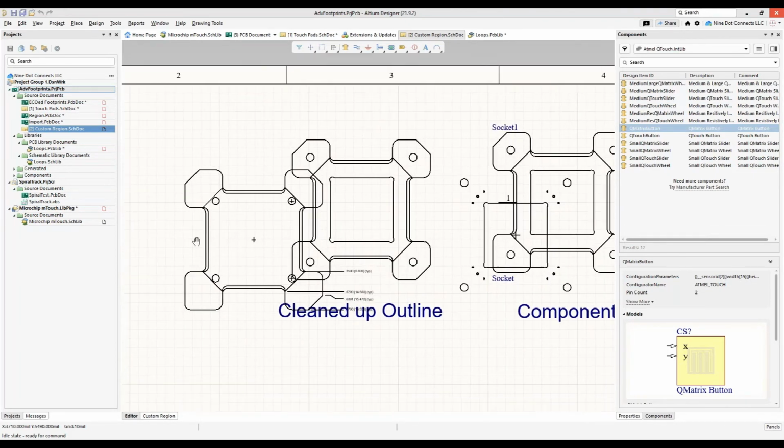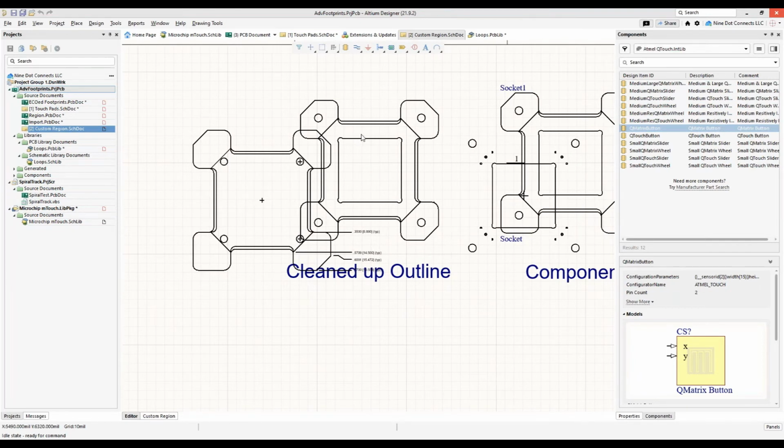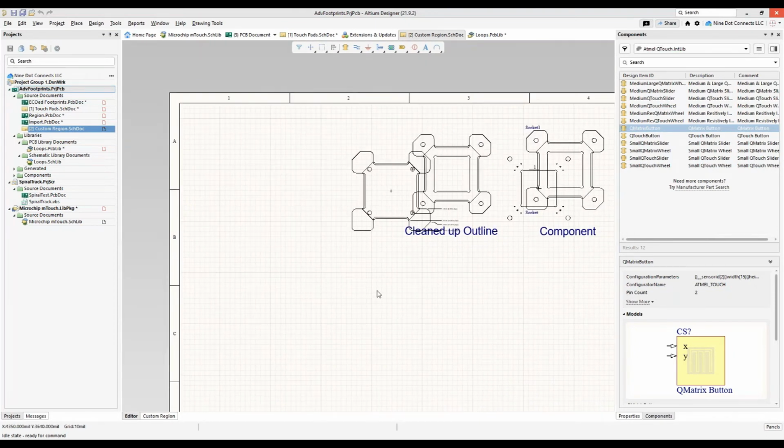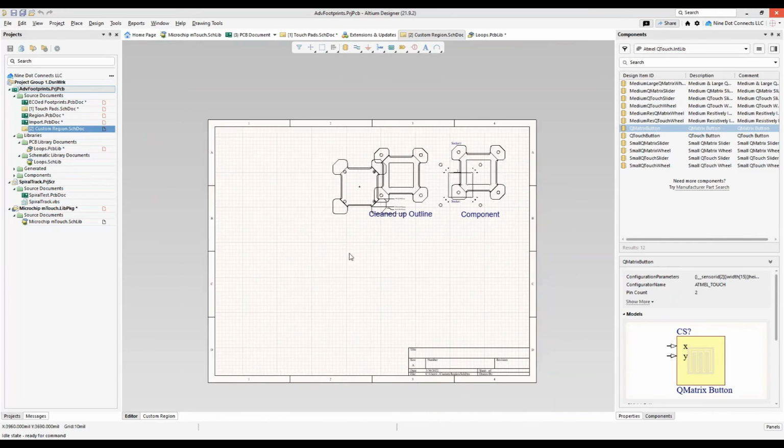The other thing too, when you bring these things in, let's assume it comes in great, looks good. Yeah, I can make this into a schematic, and then you'd copy this into the symbol library, by the way. And you may say, well, why didn't you just do it in the symbol library? The reason why I didn't do it in the symbol library is I just find that the symbol library, because we work more in the center point rather than on a sheet, it seems like sometimes it gets pushed off into a weird corner. It just seems to work a lot better when I just push it into a schematic and then copy the primitives into the schematic library. So that's why I did it here and not in the schematic library.